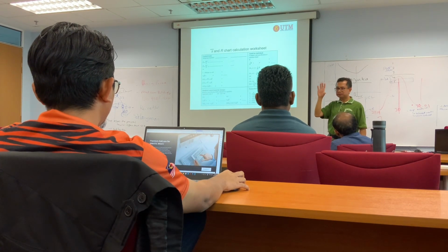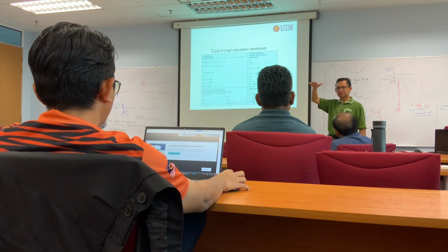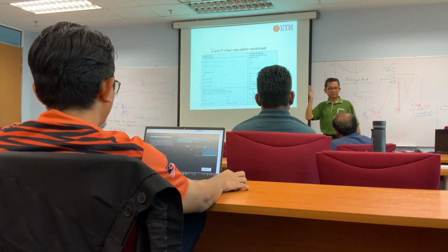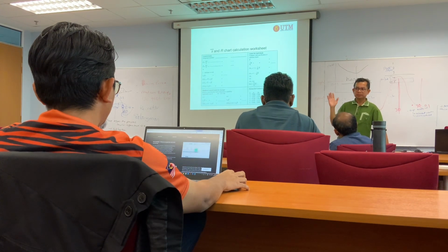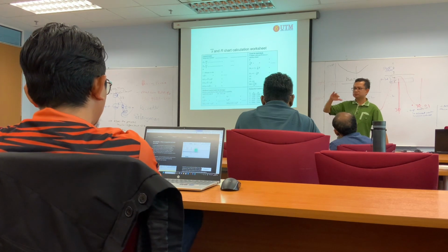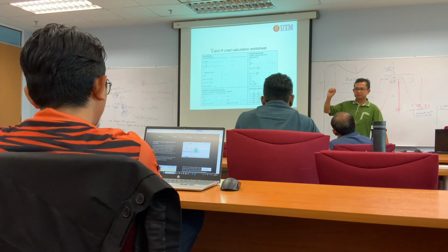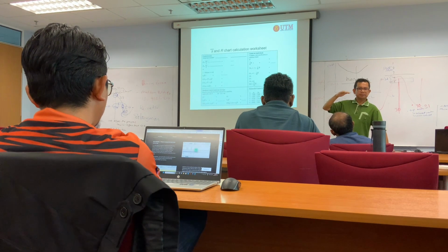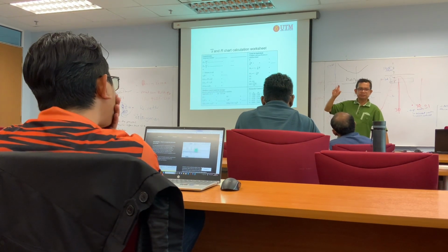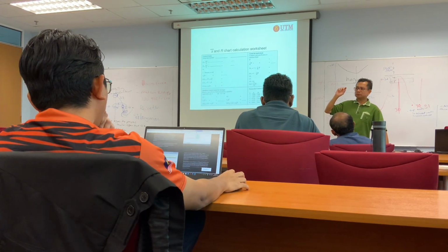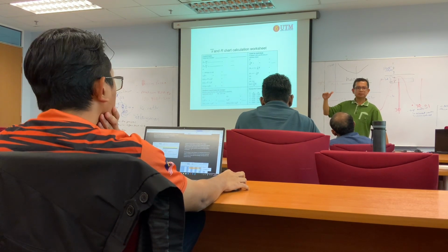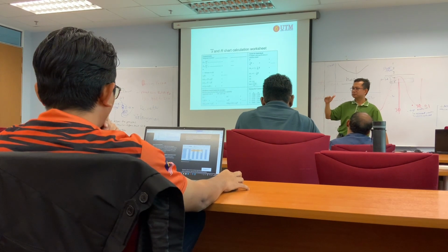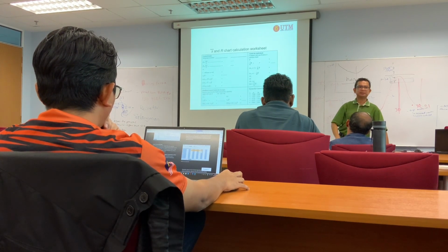So when they change the material, of course they still use mild steel, because Proton can afford those steel. I don't know today, those steel for making Azola, they can afford to use aluminium alloy. They use mild steel. So they reduce the thickness, of course, in order to maintain the strength, they have to change the composition. So when they change the composition, they got the thinner sheet metal. Why does the problem arise? They overlook the painting side.